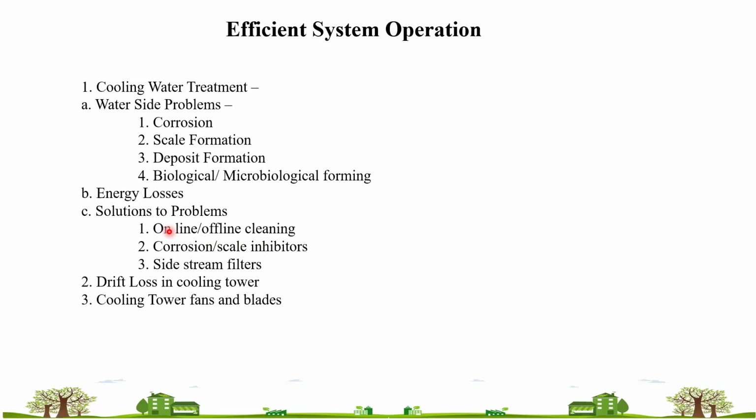So energy saving does not happen only with the equipment. You have to understand the entire system. So that's how critical thinking about the system is mandatory in energy audit. If you are replacing only IE3 with IE4 motor, or you are using nowadays EC motor and all these things, you will be saving on the equipment side, but that will not help with your energy bill or reduction in energy bill. You have to be very thorough about the system. Then you can suggest more quantum of energy savings in the entire energy audit.